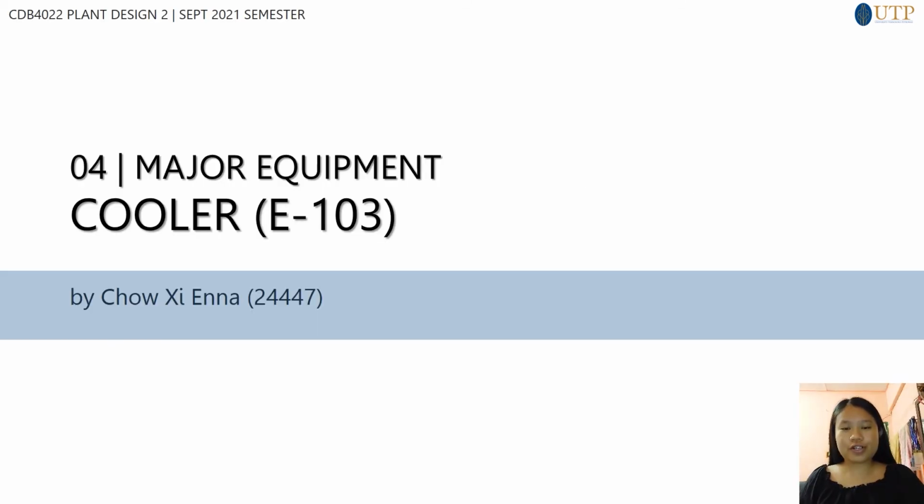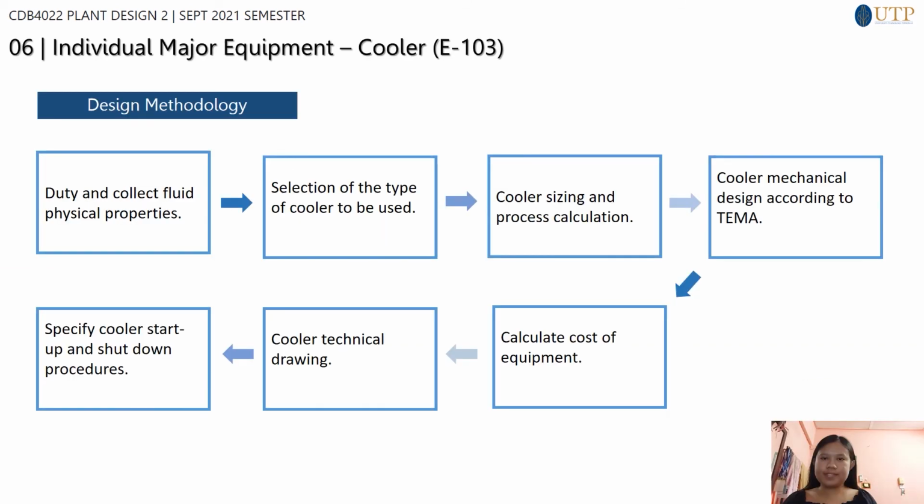The next major equipment is cooler E103. Beginning with the design methodology of cooler E103. Firstly, define duty and collect fluid physical properties. Next, decide on the type of cooler to be used.